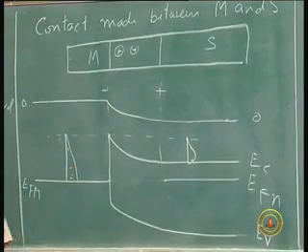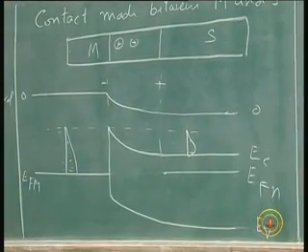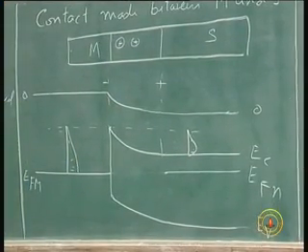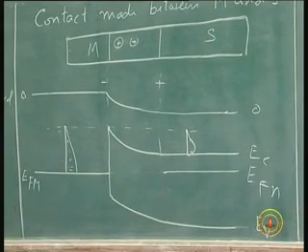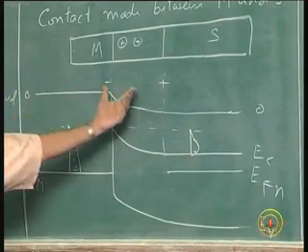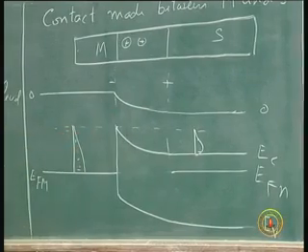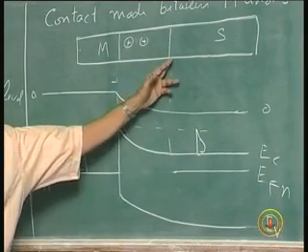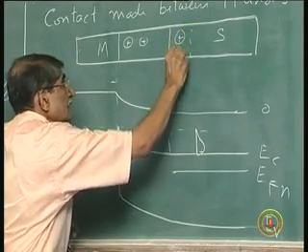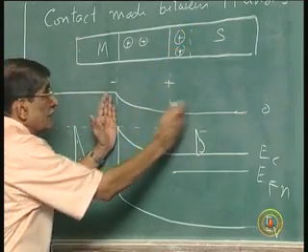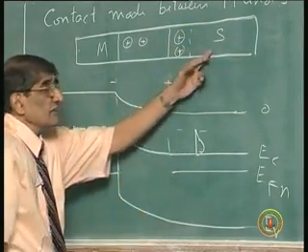It is like two resistors in series or one resistor and one insulator in series. If you apply the voltage, it will not appear across the conductor, it will go into the insulator. This is the insulator, but to hold that extra voltage, extra charges must come up. So this depletion layer will widen, uncovering extra charges, and what happens to the potential at this point?